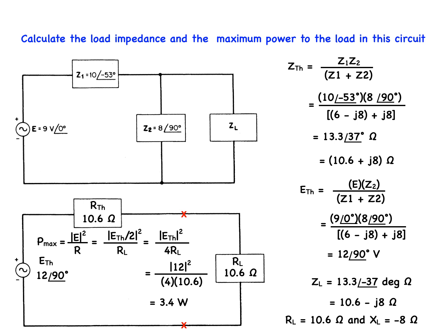The fact that the load is the conjugate of the source impedance means that the reactive current is going to oscillate between the impedance of the load and the internal impedance of the source, similar to what we have seen in our last problem. And the current delivered to the circuit is going to be at 0 degrees, or considered a real value.